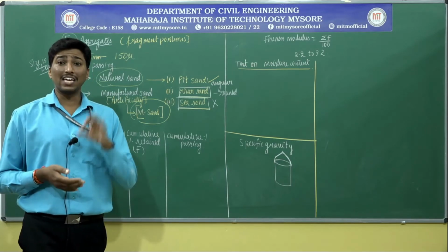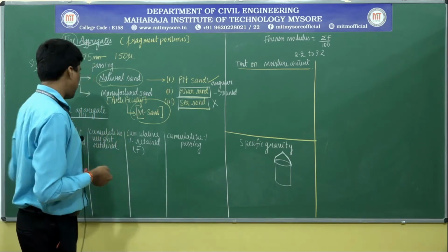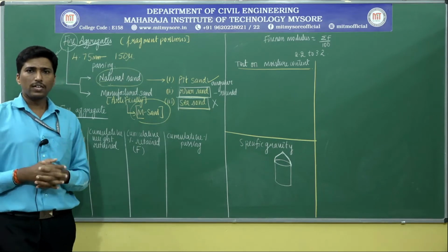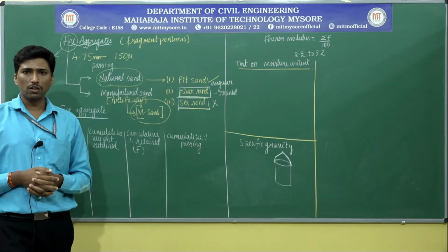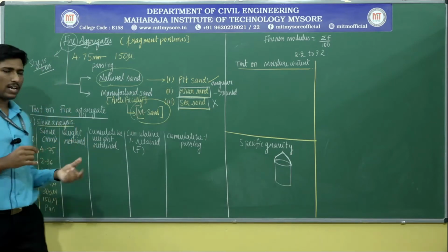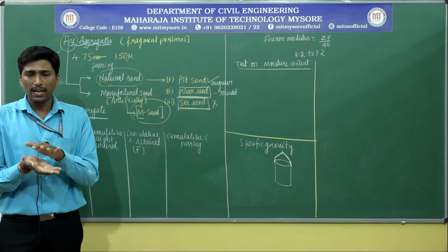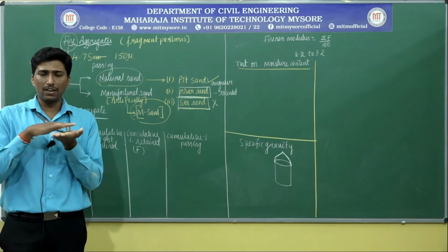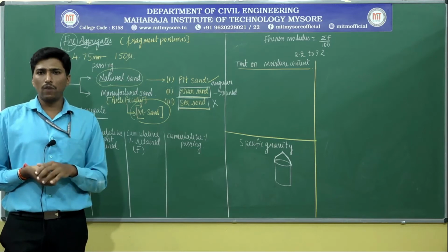That part we call grading in the materials. That is the major purpose. After subjecting it to 10 minutes of sieving, each individual sieve pan is taken out and placed into the tray, where all the material retained above is transferred. Later on they are weighed.